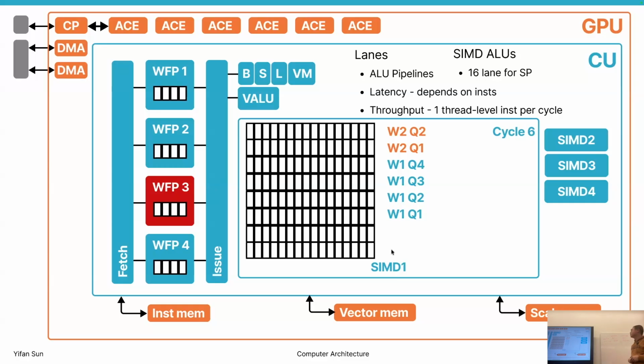Okay. So still, you see, there are more resources here, right? So it's hard to say which one has higher throughput. It's just different ways of scheduling. But definitely on this side, it's more latency friendly. That means for calculating one warp, it's just a 1 cycle thing. This requires 4 cycles.